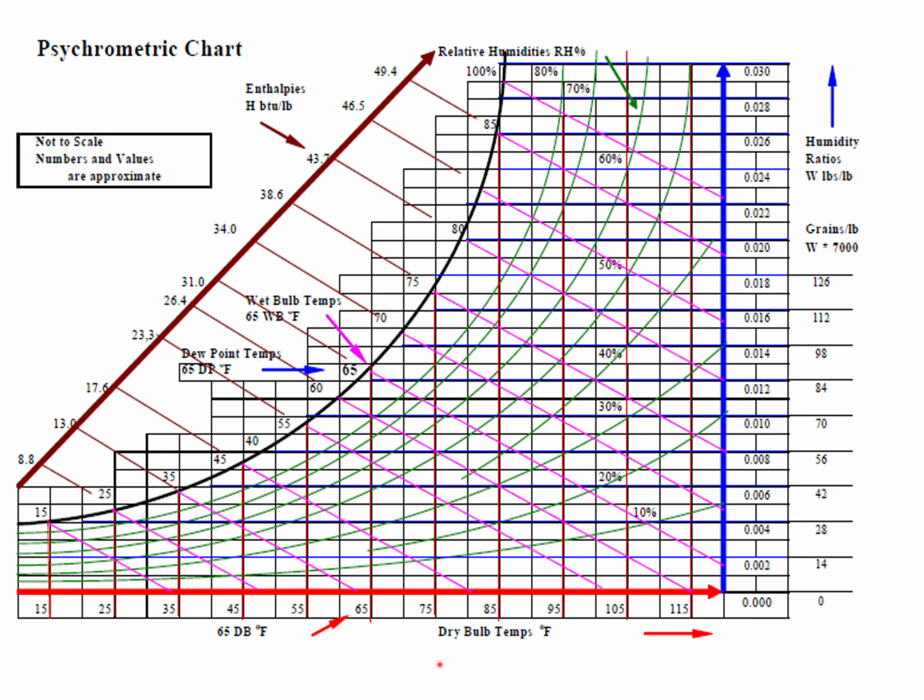But keep in mind that in this psychrometric chart, the dry bulb temperature is the x-axis, whereas the y-axis is the specific humidity or humidity ratio. Okay, that means gram per kg. Then these curved lines are relative humidity lines. You can see here that is 10%, that is 20%. This is the relative humidity line, and this is the 100% saturation line. You can see this is 100%.